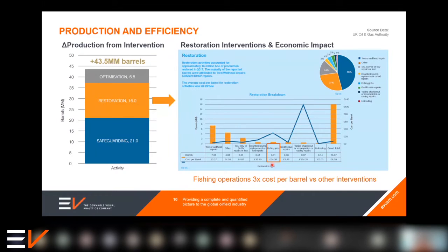But what we're going to talk about is how we can drive that cost down by making these operations more efficient and more effective in exactly the same way we did in the first case study. And on top of that, it's also worth remembering that any of these trips in hole for any of the other activities could result in a fish at any time through misfortune or an unfortunate sequence of events. So again, even in this environment, when you're not necessarily expecting a fish, being able to react and deal with it effectively plays a big part in the economic argument.